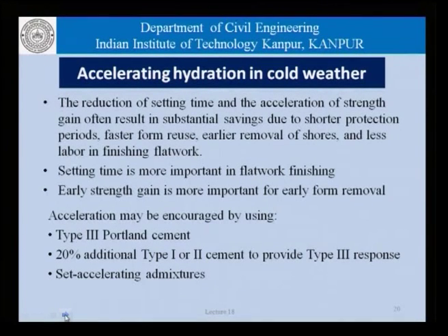We could accelerate the hydration process in cold weather, and that could be done by several methods. The reduction of the setting time and the acceleration of strength gain often results in substantial savings due to shorter protection periods, faster form reuse, earlier removal of shores, and less labor in finishing flat work.